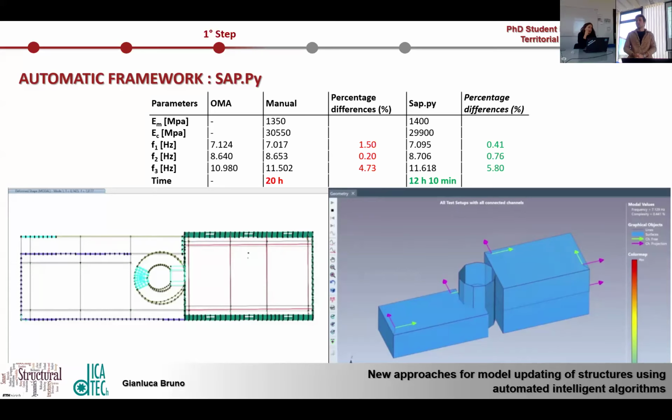Theoretically, to do the model updating, since you have a lot of sensors, you would maybe be able to recover higher modes. And of course, if you also include the mode shapes later on, you should get a better updating. What is weird to me is that you already have very good frequencies, the difference is very small, especially for the first two modes.